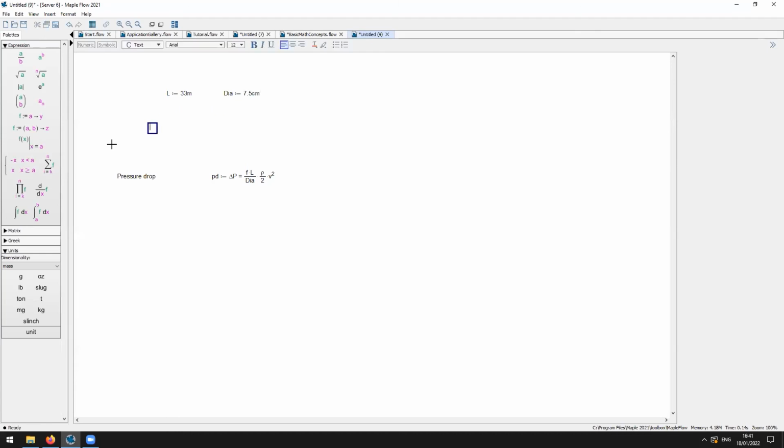And there's that parameter F there. I know that's the pipe roughness. Sorry, that's the friction factor. I think that friction factor is defined by a correlation. So I know that's governed by an equation, not a simple parameter definition. So I might type that in here. So I might say that the friction is equal to a standard correlation that I get from an engineering textbook.